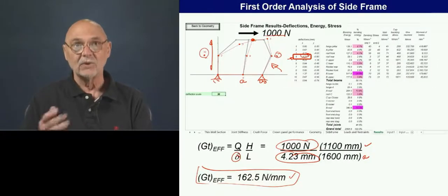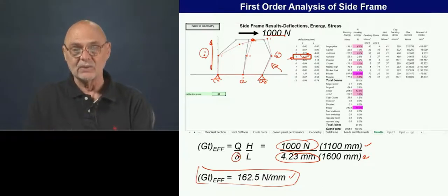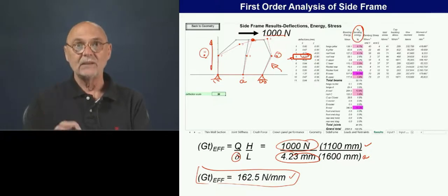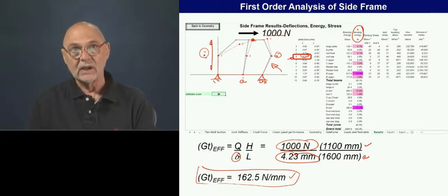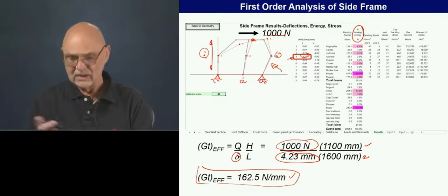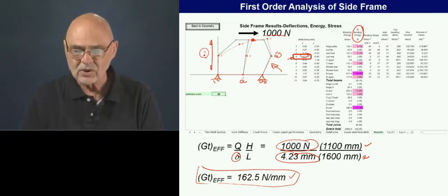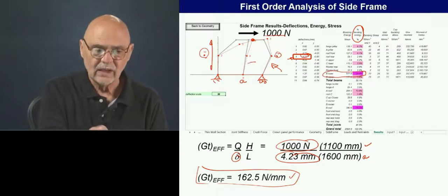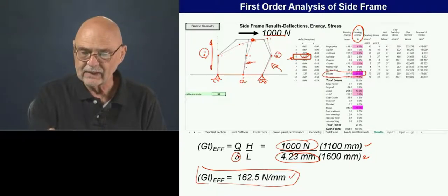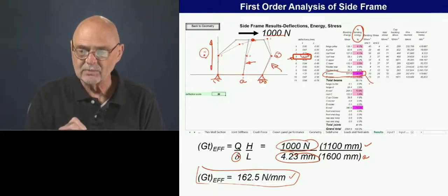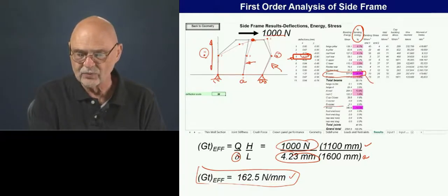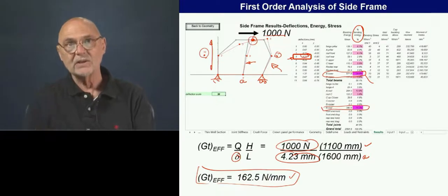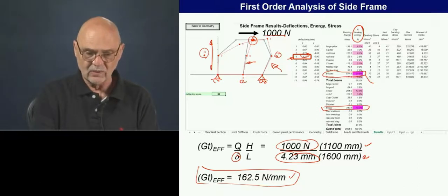Well, going back to the model, we'd use the same kind of general methodology that we talked about there. We would use the bending energy to help direct us to what would be the most valuable to improve. So here it's saying that the B pillar lower as a structure and as a beam would be important to change, and then the B to roof joint. So that would be this joint up here. So we could go in and change those, kind of see where we go with this.